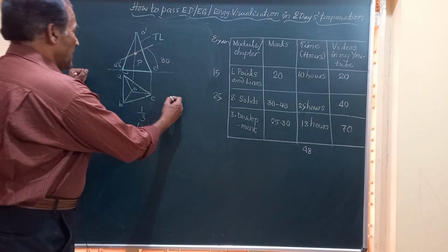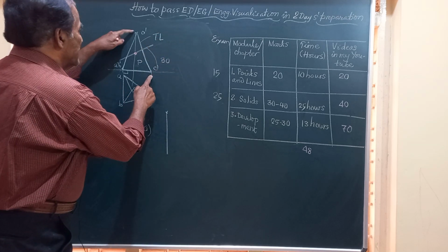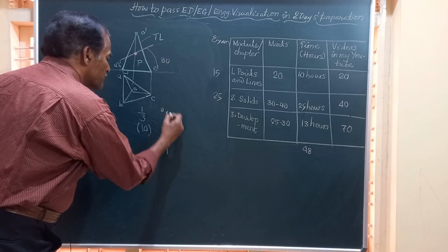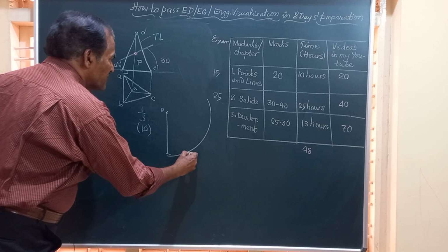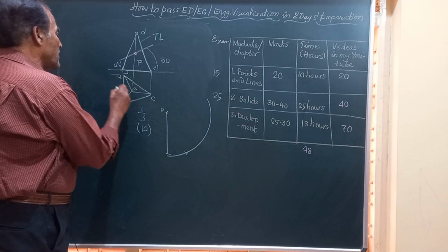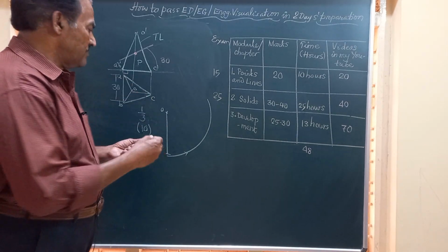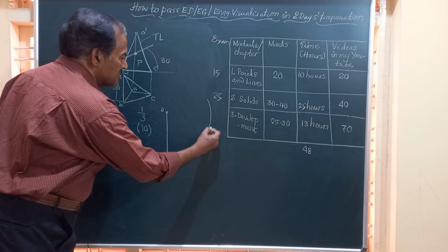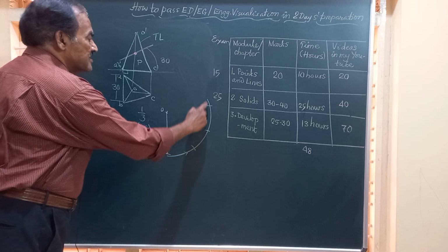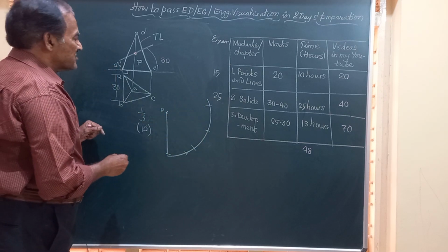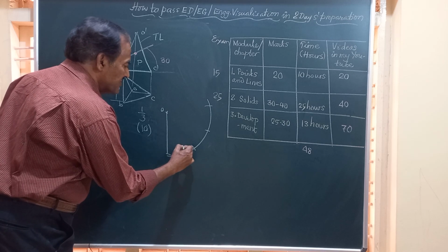Now friends, I will take this true length, simply mark the true length. Say this is what are the length you get. Here O dash C dash, mark it as O, taking O as center, this point as radius, you mark an arc. And on the arc, you step up whatever may be the size of that side. If it is 30, in a triangular pyramid, you should mark 30, 30, 30, 3 times. If it is a square pyramid, 30, 30, 30, one more you should take. Since I have taken up this triangular pyramid, I should join and take only 3 steps of 30 millimeter each.